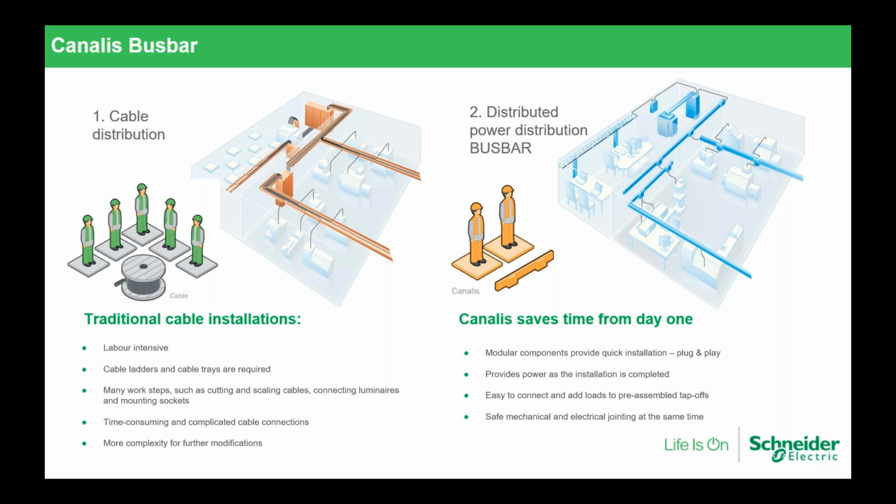And here I put in just to highlight the difference: on the left using cable and on the right using bus bar. There are several differences, and as I said, I will share more details during the next slide. But one will be the manpower that you need to manipulate the cable, depending on the ratings that you need. On average, let's say 5 people to manipulate the cables, and on a bus bar rating, you need 2 people to install and mount a bus bar.